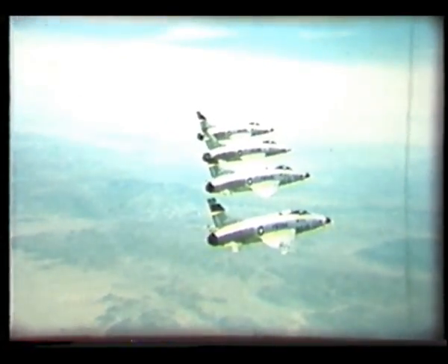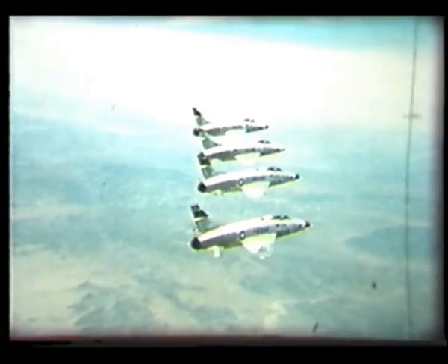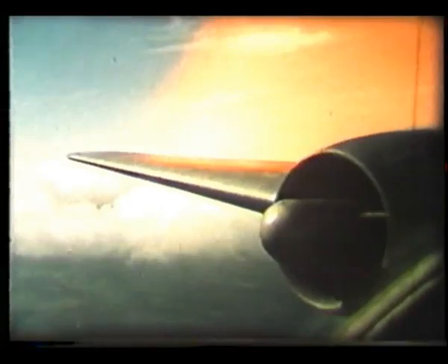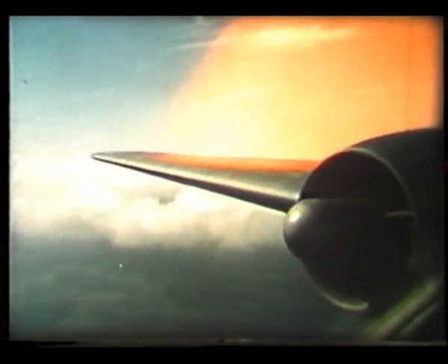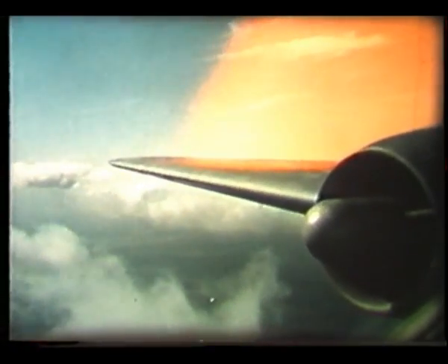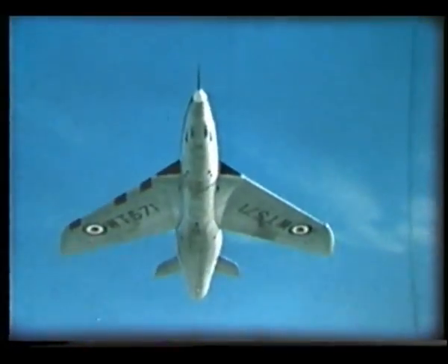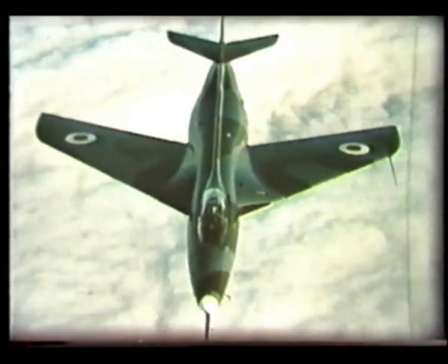All these improvements in design are reducing shock stall troubles in the difficult earlier part of the transonic range. Still, faster flying is only possible when wave drag can be reduced. The drag caused by the shock waves changing kinetic energy into heat. A new design principle helps to do this. Area rule.